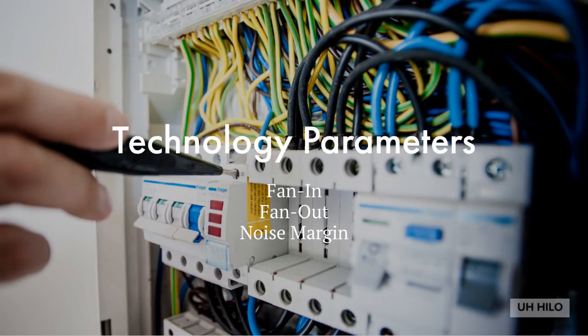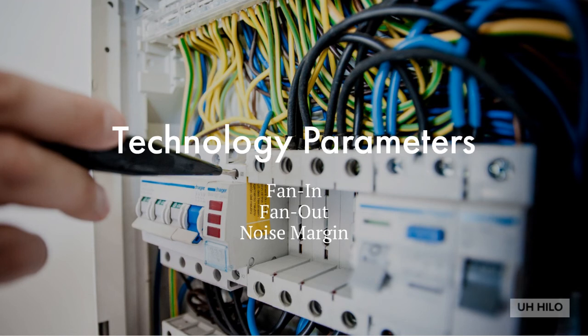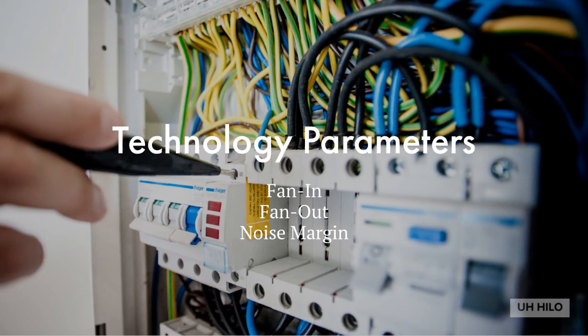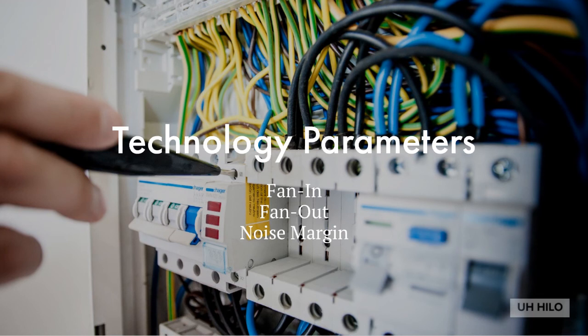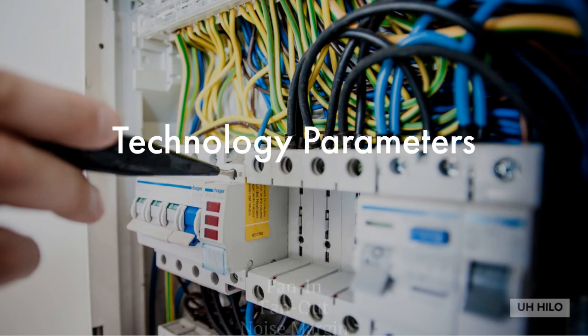The parameters that are important in the design space are fan-in, which specifies the number of inputs available on a gate. Fan-out specifies the number of standard loads driven by a gate output. Maximum fan-out for an output specifies the fan-out that the output can drive without impairing gate performance. And noise margin is the maximum external noise voltage superimposed on a normal input value that will not cause an undesirable change in circuit output.